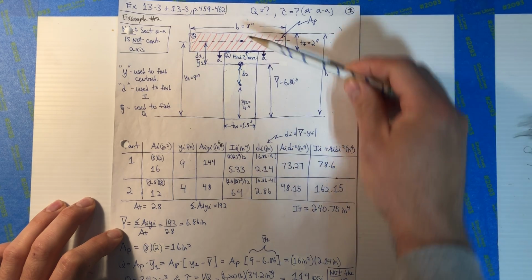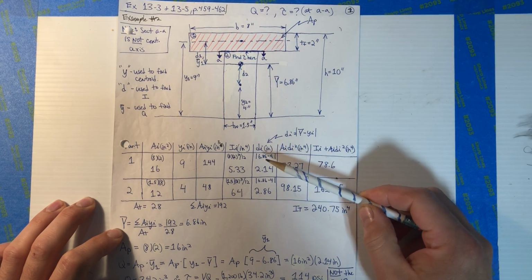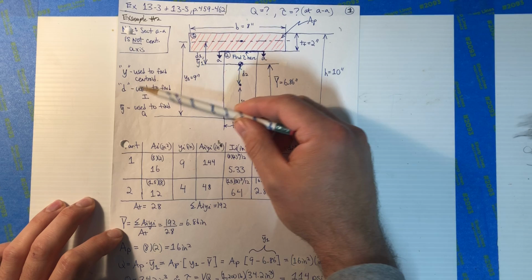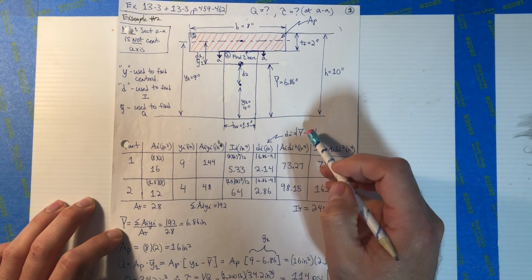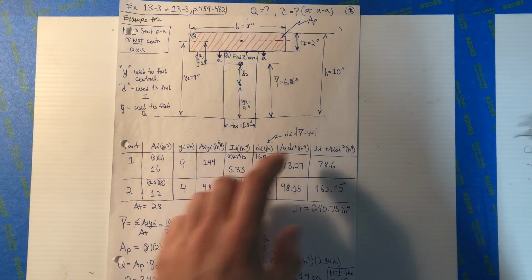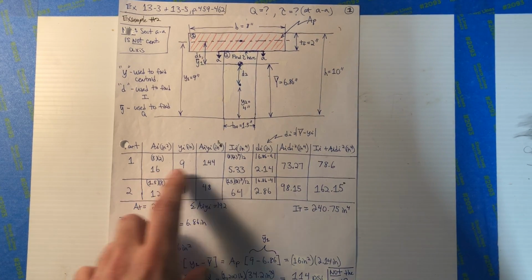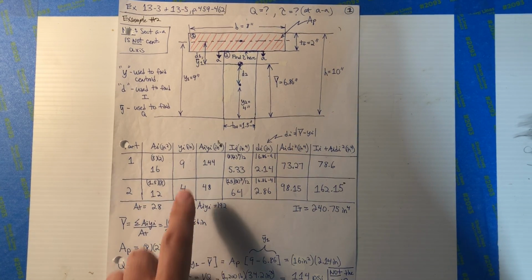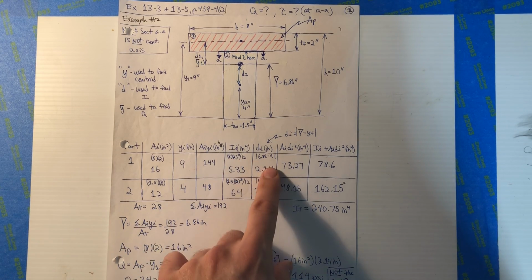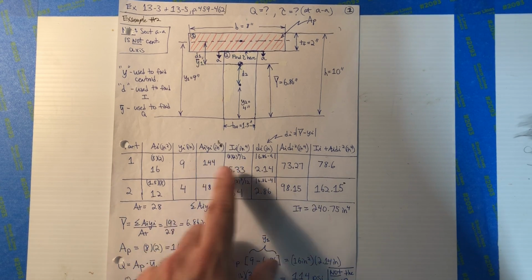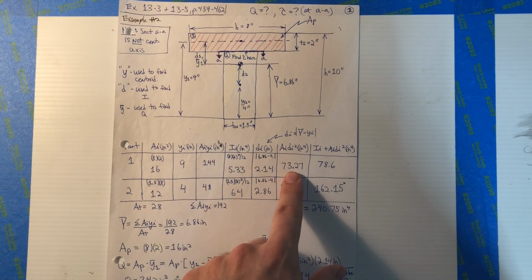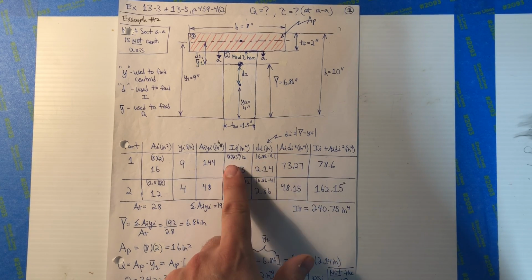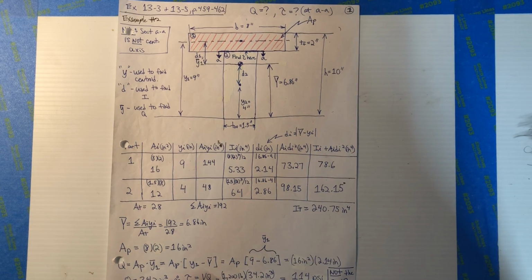You can calculate Ii for the components, okay? di, if you're not so comfortable with that, just do this absolute value where it's the centroid location minus Yi, right? So it's simply this minus that, the absolute value gets you that. Then you multiply this times this squared, get you that.